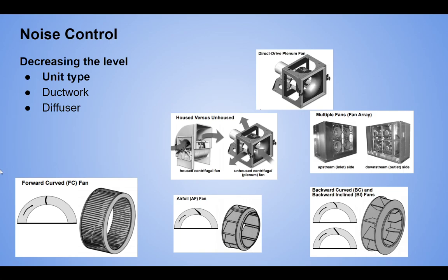Every once in a while, if I know the mechanical equipment is going to be close to an acoustically sensitive room, I will forego backward curved and airfoil. They just make a sound profile that's a harder issue to tame. So these are spinning this way.